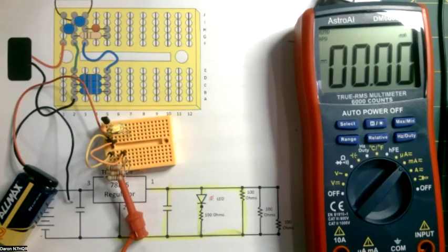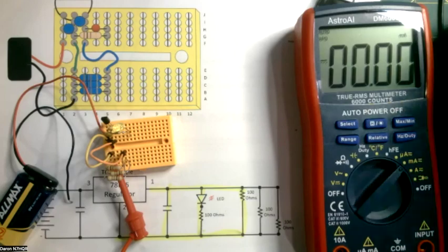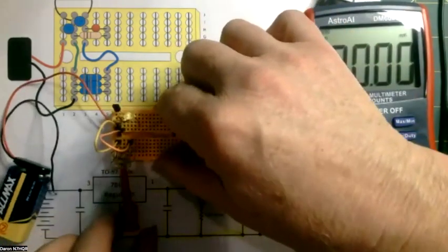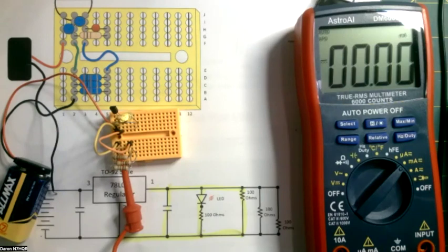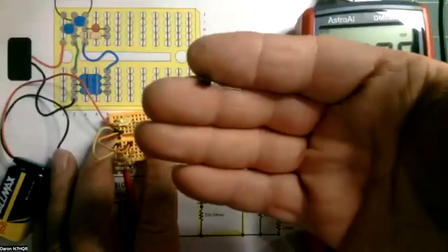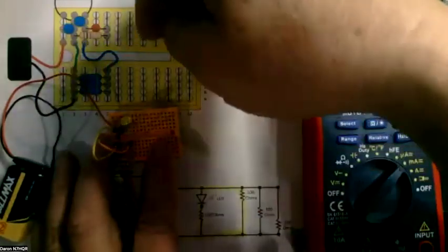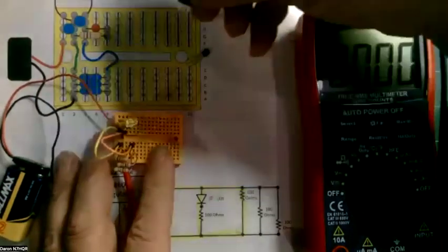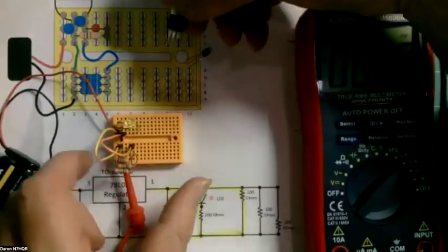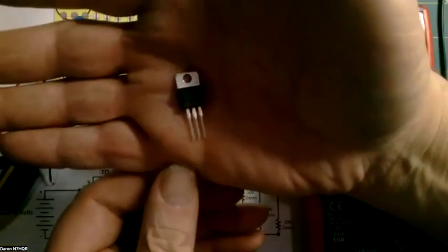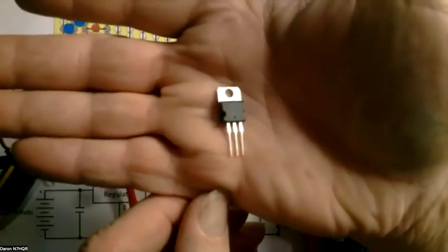So anyway, folks, we have exceeded the capability of our little 78L05. Now, Darren, just grab your 7805 and stuff in there. This component may be warm, so if you're taking that out and putting the other one in, just understand that might be warm. Yeah, disconnect your power. My power is negative leads off. Oh, okay, good. So here's the larger 3-tab regulator.